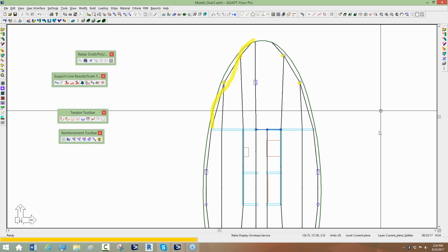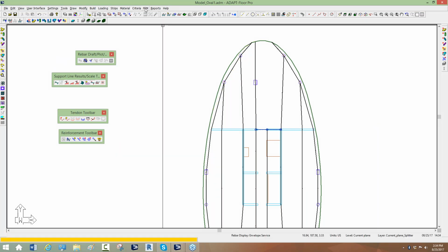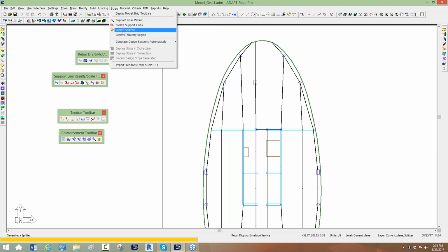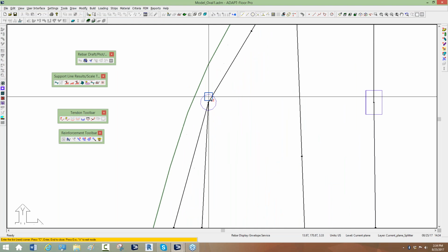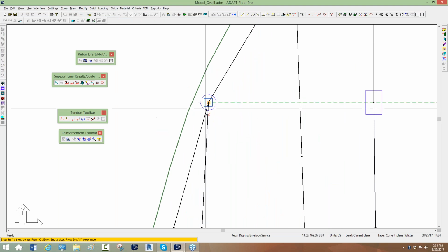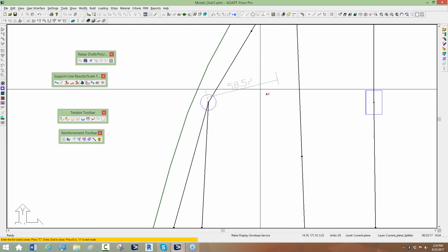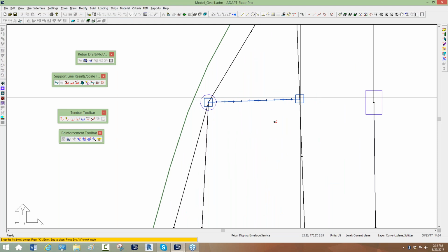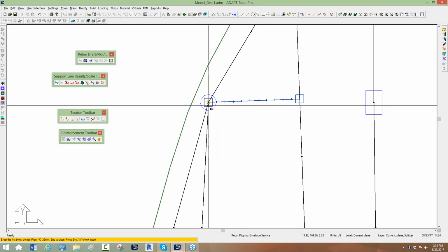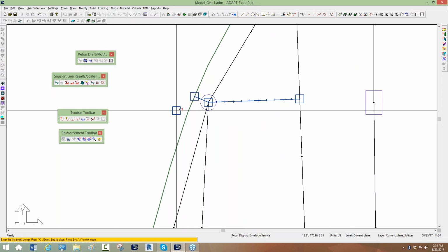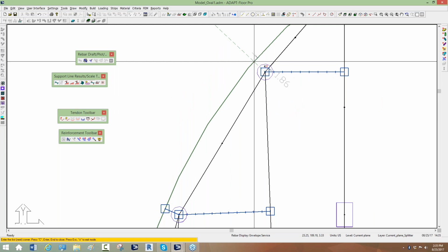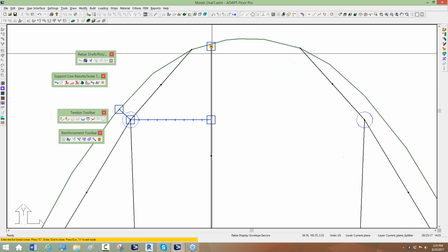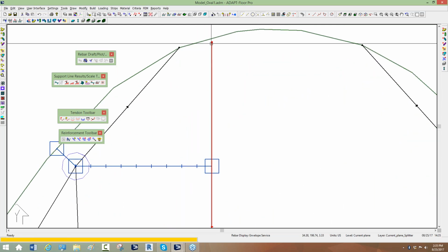So I'll go ahead and do that, and we'll go to strips, splitters again. This is already set to Y direction. So here I'll start here where this line terminates. I'll go to the continuous support line to one side, and on this side, there's a slab edge, so I'll go to the slab edge here on this side, and then I'll do the same thing here, like so. By the way, this needs to be extended up.